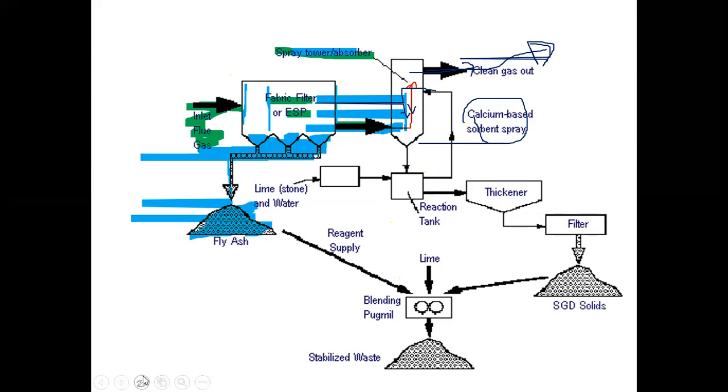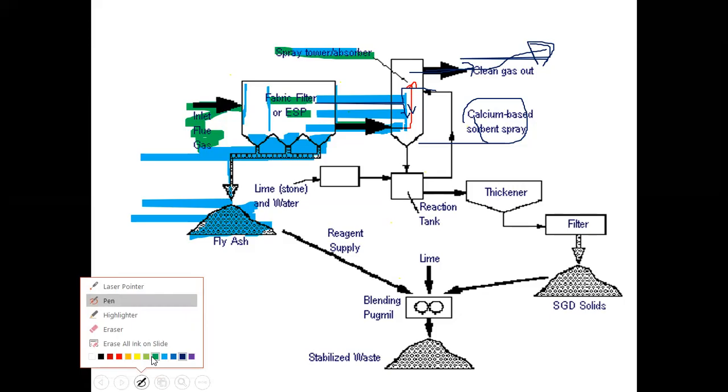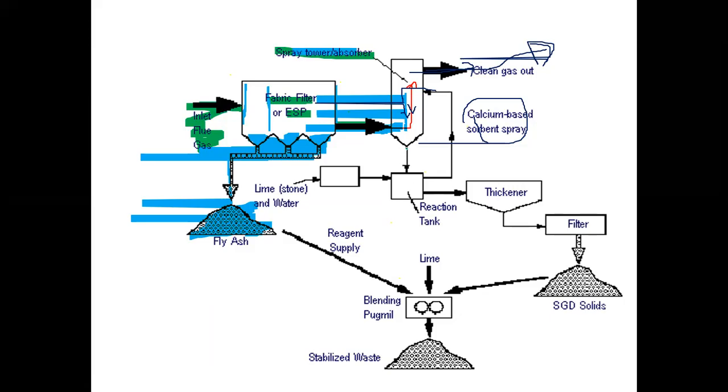Now look at the bottom of the wet scrubber. Here calcium sulfate is formed, then this solution can be sent to a thickener, like a sedimentation tank. At the bottom of the thickener or the sedimentation tank, we can concentrate the calcium sulfate solution.